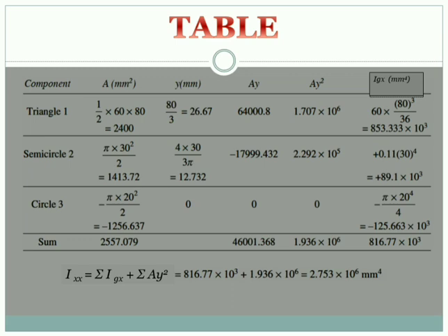Then y. Okay, so y1, y2, y3, all the three values have to be located with respect to which axis? Yes, with respect to your given AB axis. Okay, no need to take any axis in this example, because already they have given an axis, and about that axis itself we want to find the moment of inertia. Therefore the y1 value will be equal to h by 3, that is 80 by 3. Then we will get next value a into y and a into y square.